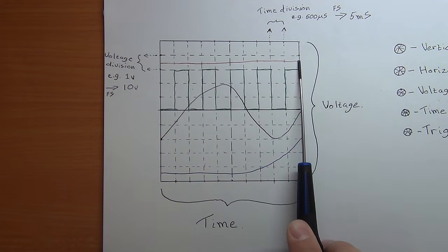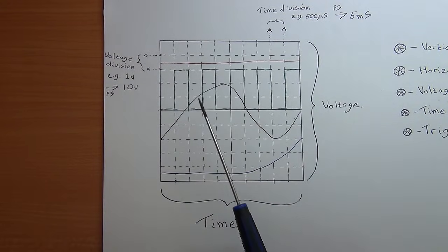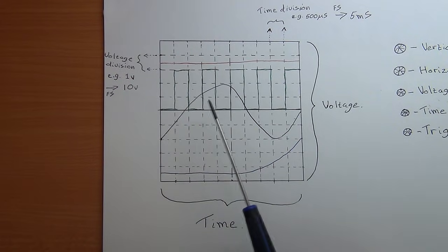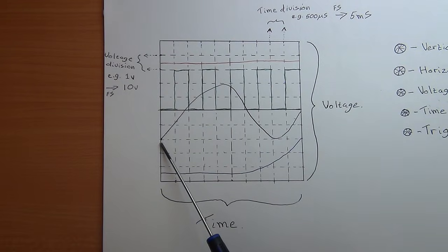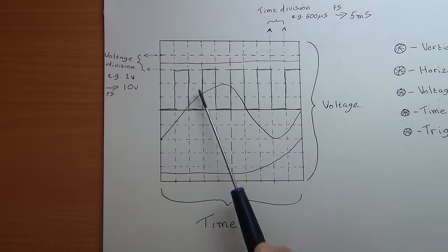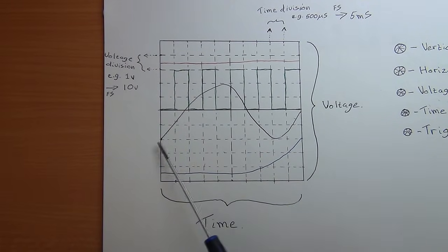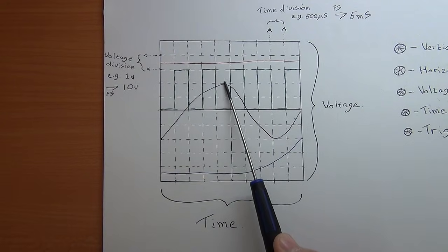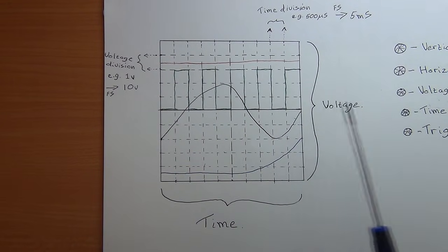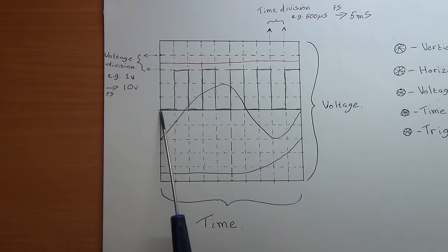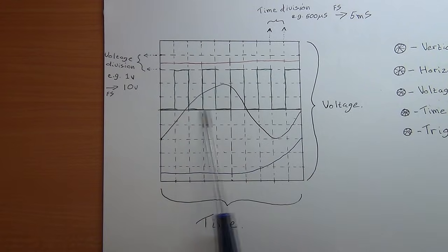It's just going to be a straight line. If you had to connect your oscilloscope up to, let's say, if you could connect it up to your mains electricity safely, and you're looking at the signal of the AC, you would see a sinusoidal wave appearing on your scope. So it'd be something that would be going positive and then coming down negative. Now, something else to highlight is that you have a kind of middle line on your oscilloscope, which in essence represents your kind of 0-volt line. So above would be positive, below would be negative.